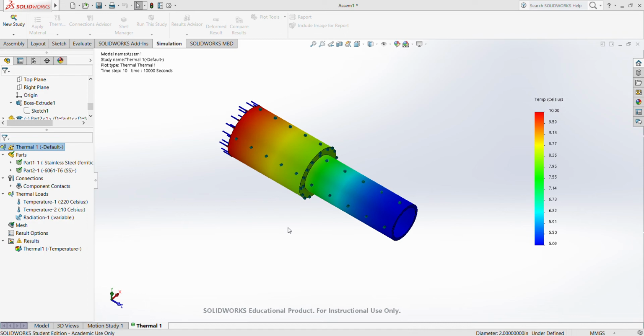What you might want to do is select another probe point. You might want to select a warmer one, because you want to assure the whole thing reaches 20. So you might want to select the probe point that is on the warmer side instead of in the middle to assure that the whole cat bed is under 20 degrees. Or you might want to select a point out here somewhere, right?